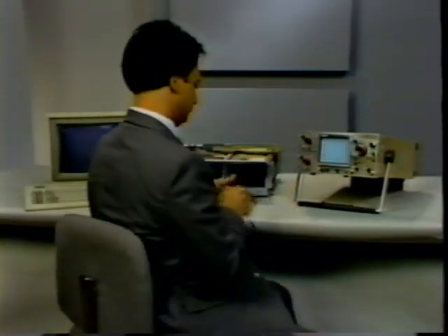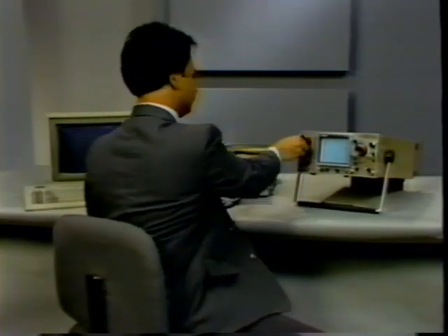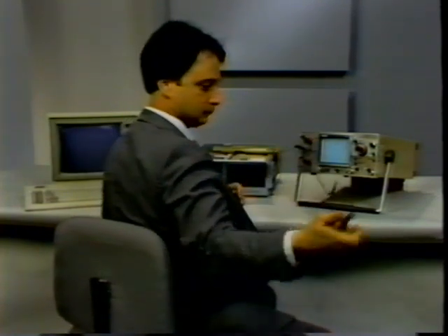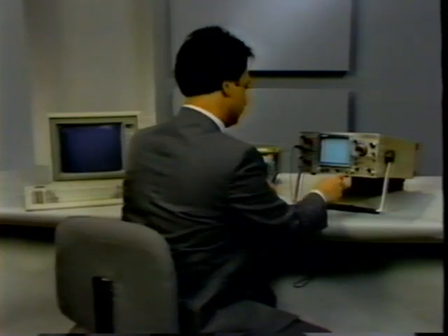Most oscilloscope manufacturers recommend that their scopes be calibrated once a year. A skilled oscilloscope technician should perform this alignment. Do not attempt this procedure in your shop. There are two adjustments that you can make to your oscilloscope. These are trace rotation and astigmatism.